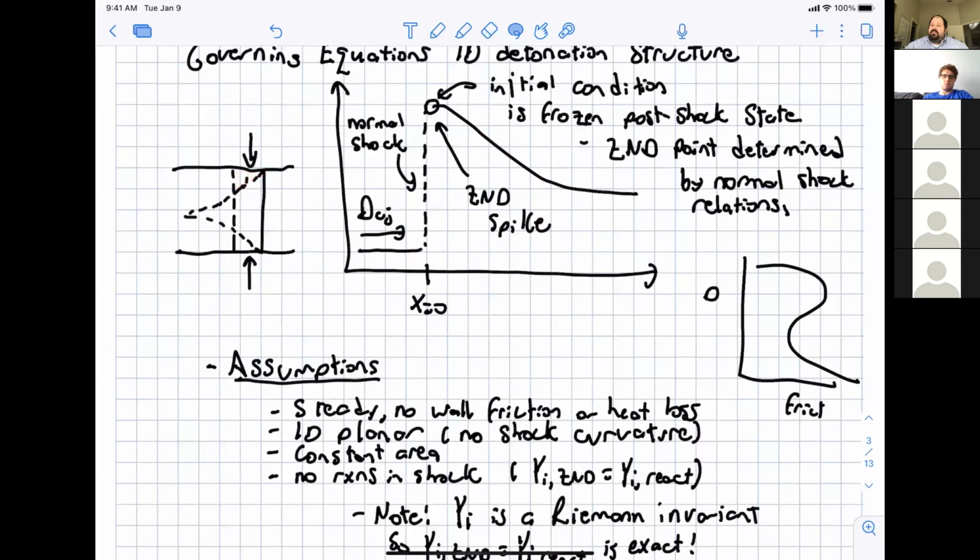When you're calculating the strength of that normal shock, are you looking at the sound speed of the non-moving material? Because the temperature is much lower, because we're saying that the detonation is sonic in the reacted area, but in front of it you've got non-moving material at some low temperature in comparison. So if I want to calculate the Mach number, would I calculate it using that unreacted material for that pressure jump? Yes, so you would base the shock jumps off of the cold reactant state.